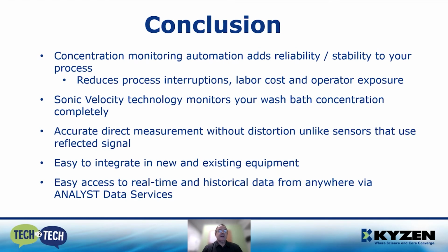In conclusion, concentration monitoring automation adds reliability and stability to your process, reduces process interruptions, also labor cost, and more important, the operator exposure to chemicals. That's a great benefit. Sonic velocity technology monitors your wash bath concentration completely, not just the solvent layer or a specific component of the bath. It monitors the entire solution.